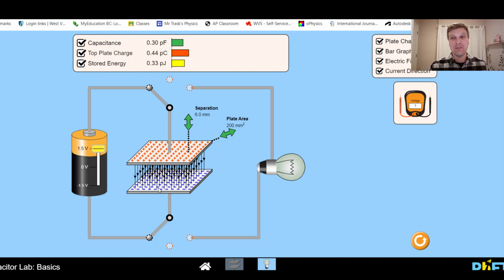There are protons and electrons there, but there's no extra electrons. So the first electron that shows up is going to think this is a great place to be. And then the second and the third and the fourth and the fifth and eventually the 100th and the 1000th and the millionth and the billionth electrons start to show up. There's more and more electrons piling onto this plate. Well, we know that electrons don't like other electrons. They're going to repel each other. Eventually, so many electrons build up on this bottom plate that no more electrons can fit. Even though the battery is pushing with a certain amount of voltage, there's like a back pressure created by all the built up electrons on the plate that's pushing back against the battery, which essentially prevents the flow from continuing.